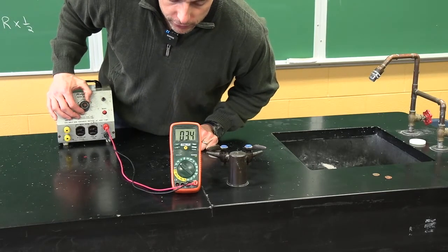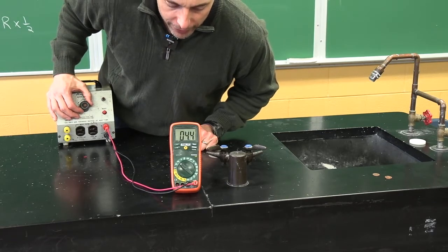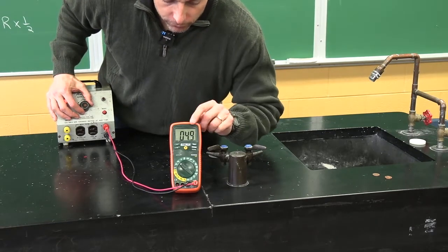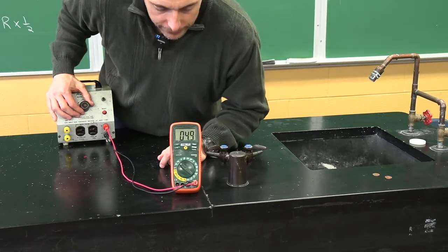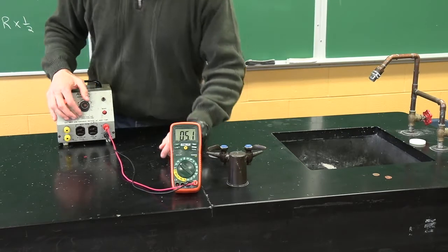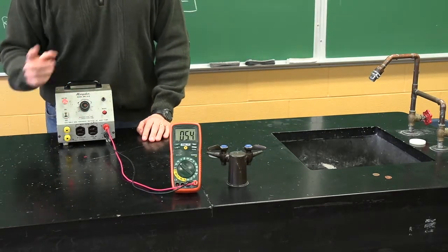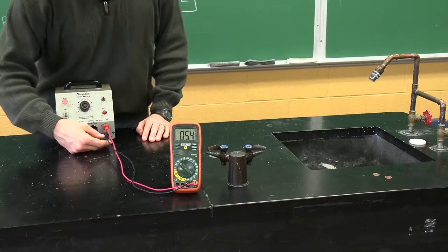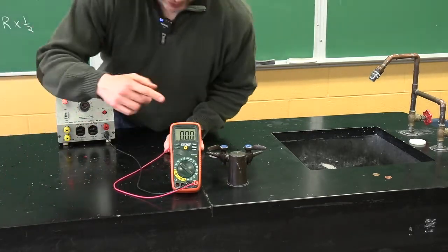So what I'm going to do is turn this up to about, you see, I could go 5 volts, I could go 14 volts. I'm going to make about 5 volts on the voltmeter right here. And the other thing I want to point out, an important thing, is that voltage is always 2 prongs. Okay, so I cannot get that voltage by just plugging in one wire into the power supply. You see, now I get 0.